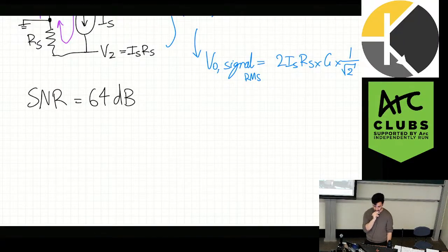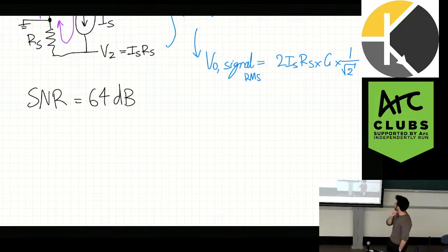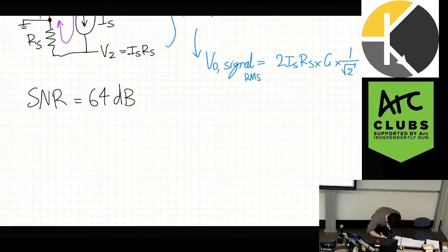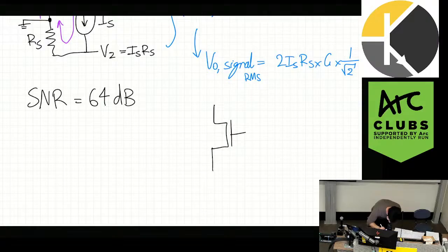Okay. Now, in terms of the common mode rejection, what internally to an op-amp causes the common mode rejection ratio to decrease with frequency increase? What happens as frequency increases in an amplifier is the parasitic capacitances become a problem, right? At high frequencies, those parasitic capacitances look low impedance. They look very attractive. So you imagine if you have something that looks like this, and you have parasitic capacitance that sits here.